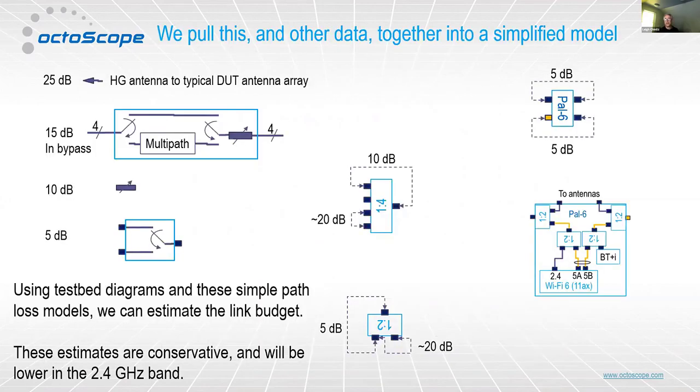Again, we have a lot of different things, but all of those fall under that big bucket of stuff between the transmitter and the receiver, and you simply add up all of them in order to create your link budget. So you'll understand the full path loss by including all of those losses,